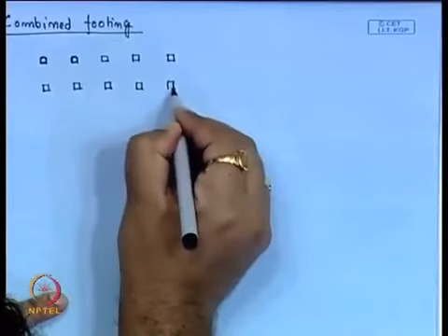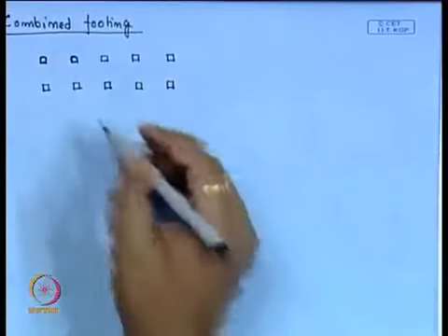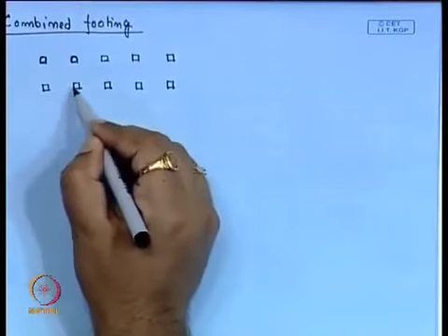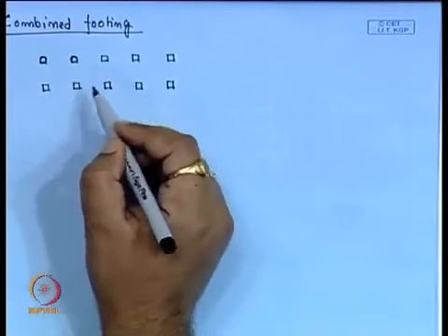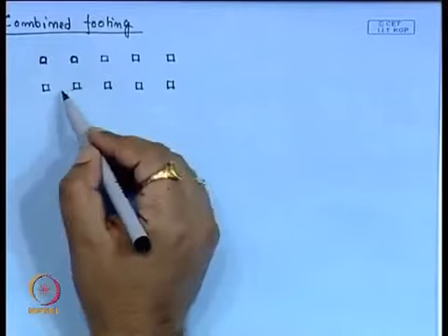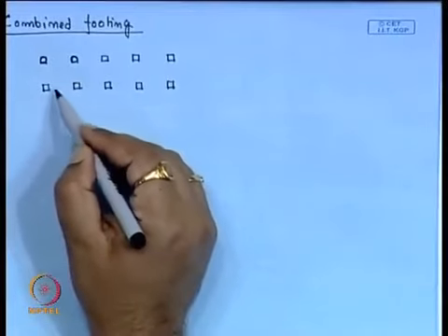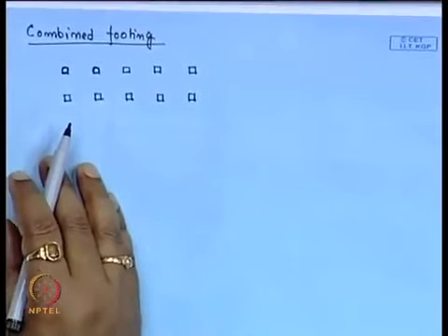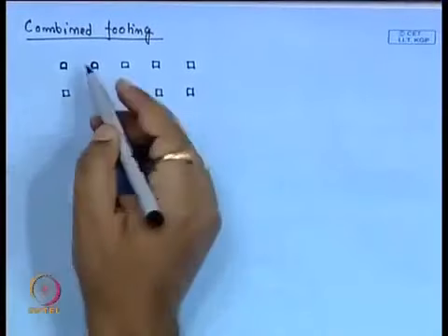Now, if we want to design isolated footings, and the spacing between these columns is very small, then it is obvious the influence zone of each column will overlap. So, there is a chance that there is an overstress zone.